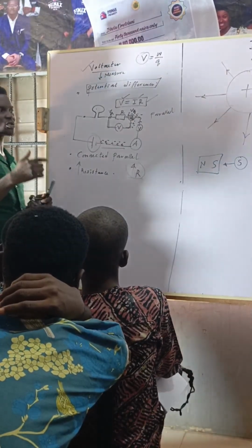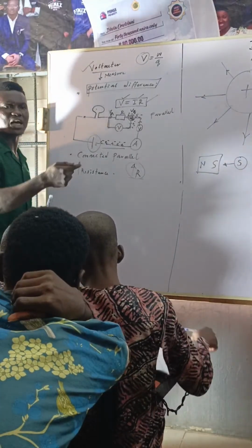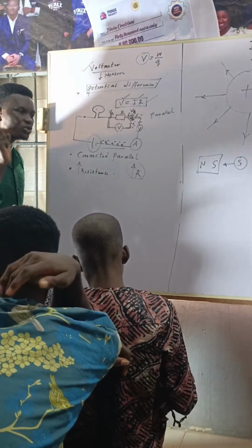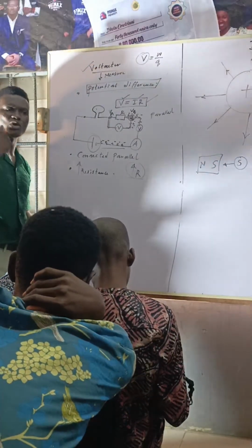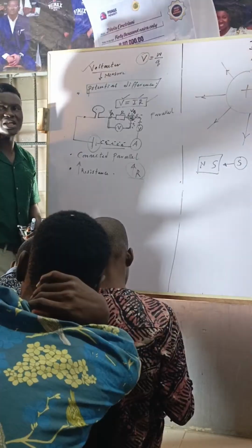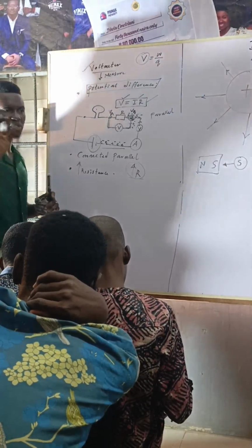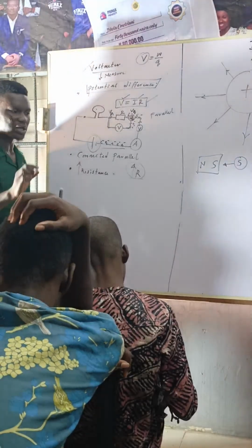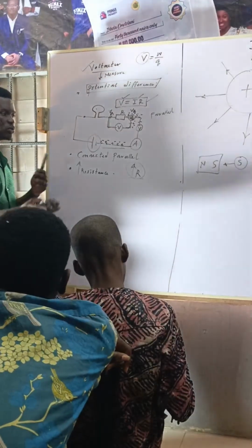So, if they ask me in an exam why is potentiometer used instead of voltmeter, it's because there is no ideal voltmeter. Current always flows through a voltmeter, no matter how you prevent it. But potentiometer does not draw current. That's your answer. Potentiometer does not what? Draw current. I saw most of these questions during my time, so you better know what we are doing.